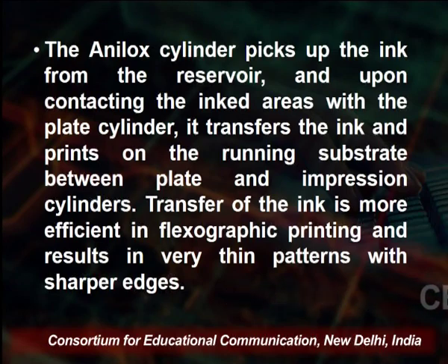So, we have an impression cylinder and we have a plate and we have a substrate. So, when it is rolled, then it gives the impression on the substrate. The transfer of the ink is more efficient in flexographic printing and results in a very thin pattern with sharper edges we can get through it.